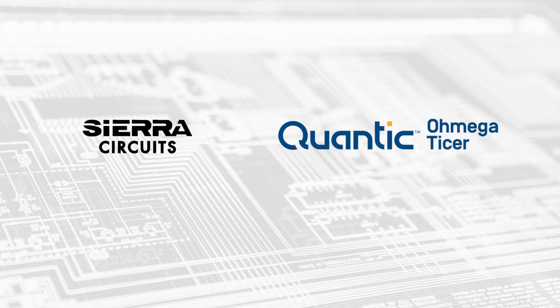So instead of having a reference plane, signal, ground plane, you'd have a reference plane, signal, ground plane, signal, then ground, or reference plane and ground plane, power plane, excuse me. So you have to add a couple of extra layers in there if you want to do decoupling capacitance with a planar capacitor. But usually the overall performance can justify the additional layer.